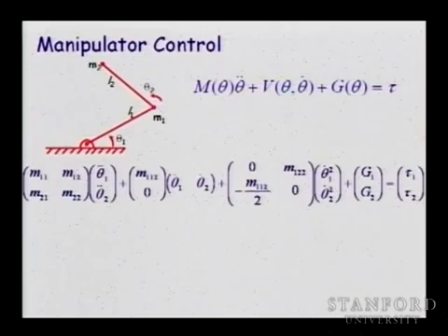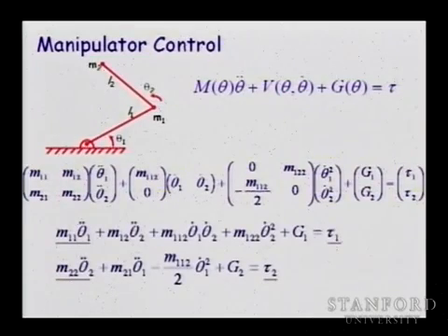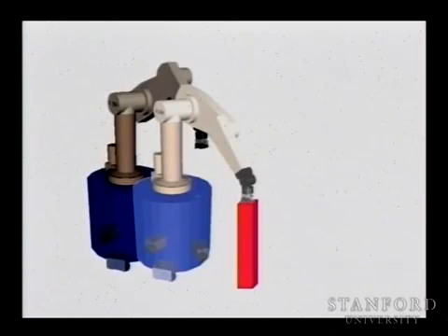And you can see that the equation of motion for 2 degrees of freedom comes to be sort of 2 equations involving not only the acceleration of the joint, but the acceleration of the second joint, the velocities, centrifugal Coriolis forces, and gravity forces. And all of these will have dynamic effect and disturbances on the behavior, but we will analyze a structure that would allow us to design torque 1 and torque 2, the torques applied to the motor, to create the behavior that is going to allow us to compensate for those effects.